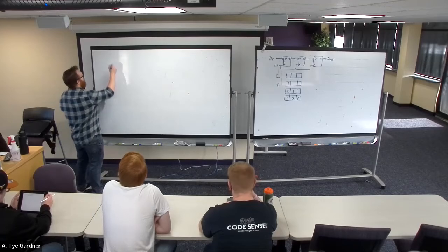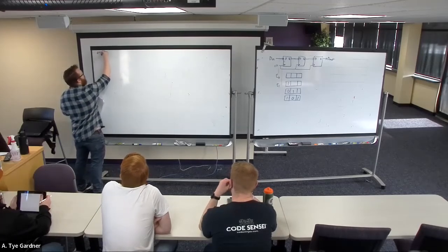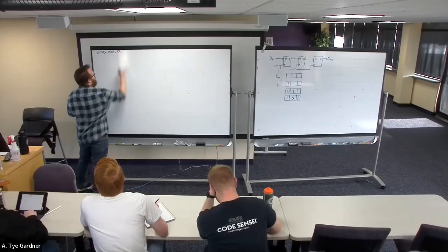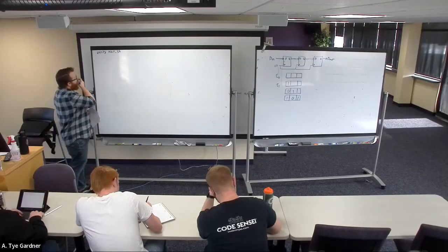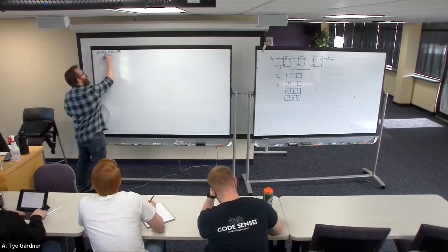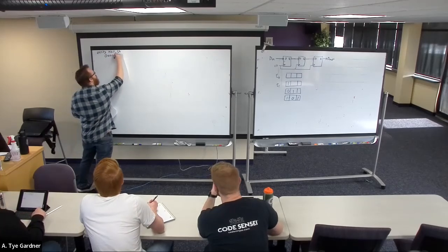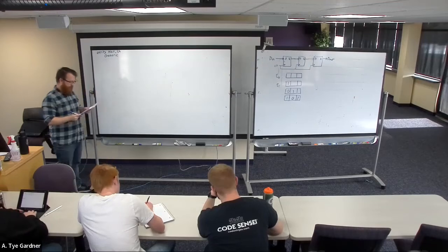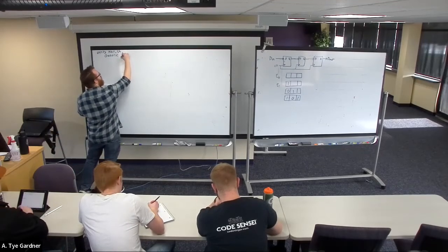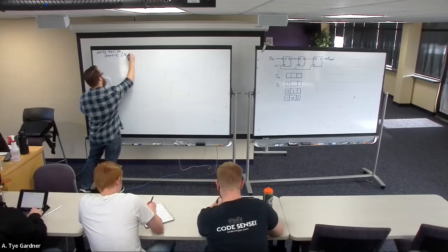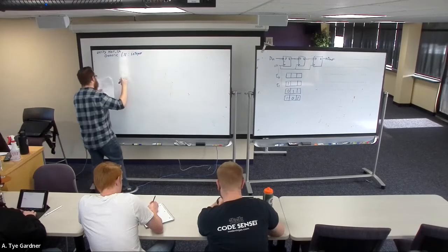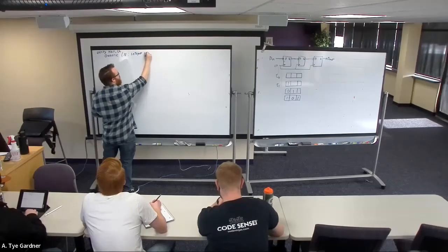So what we do is when you have the entity, we're going to call it n-bit shift. Normally we would have the word port here, and we would list the ports. We're going to introduce a new type of port called generic. In this case, I'm going to have a generic that is going to be n. It is an integer, and its default value is 16.